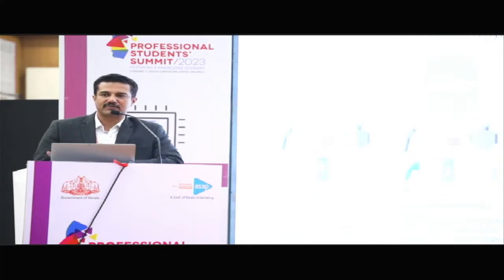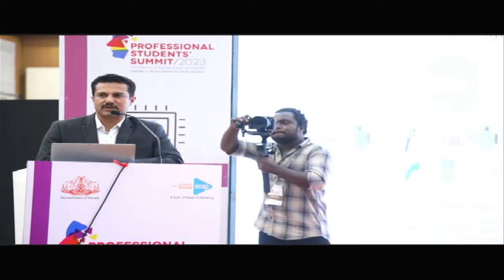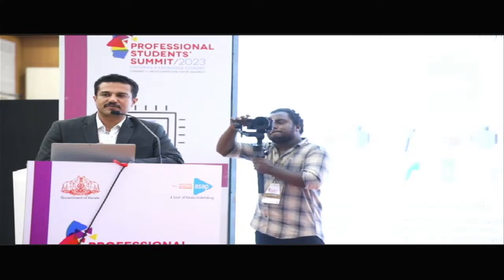Different types of hybrids, different types of electric vehicles. One is a hybrid EV, where you will have the rechargeable battery, electric motor, as well as the internal combustion engine. Both will work together. And there are plug-in hybrids, wherein the difference is I can plug in or charge the battery in the vehicle as well. So it will have an internal combustion engine and a battery, but the battery can be charged from an external outlet. On the hybrid vehicles, the battery is charged by the regenerative energy from braking and while you are cruising. So that's the difference between hybrid and plug-in hybrid.